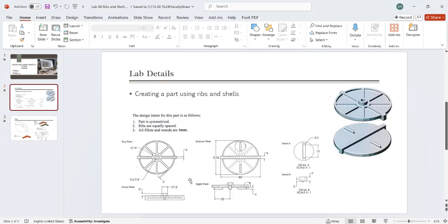The next feature that I'm going to draw is this 12 millimeter diameter circle with 5 millimeter width from this top surface. If I calculate the total length from the base plane that I'm going to select, that will be 5 millimeters plus 5 millimeters, which is a total of 10 millimeters, minus 2 millimeters. So that will be 8 millimeters.